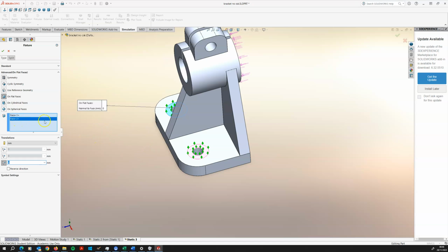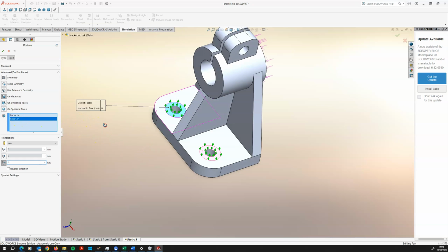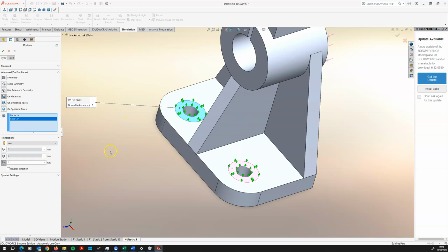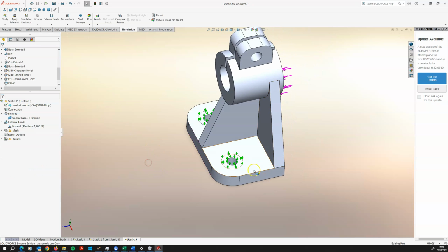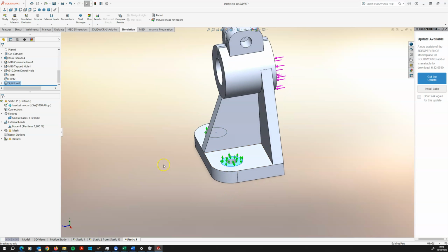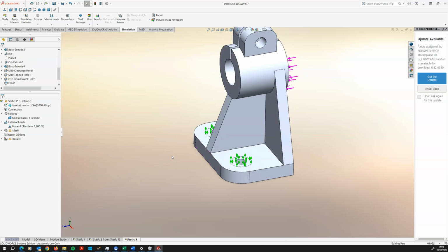And that's exactly what the roller slider fixture would do as well. It would take those areas and prevent them from moving perpendicular to themselves. Okay, so that's like your bolt and your washer going down screwed into a threaded hole or something. Would prevent this from lifting up in the Y direction. Okay.